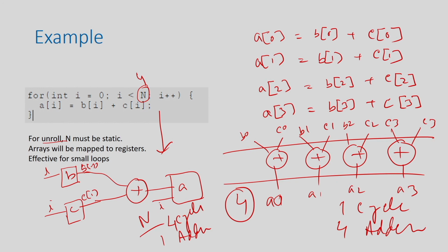But try to understand that although I get the maximum timing benefit, my resource requirement also increases by the same factor, right. So, the performance increment in terms of timing or latency is the same factor as the resource requirement. Okay. That is something obvious, because you want to execute in parallel.